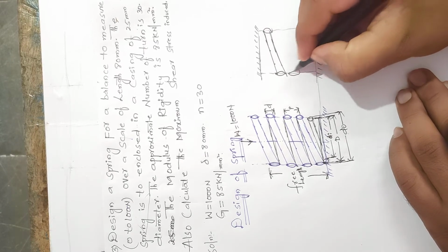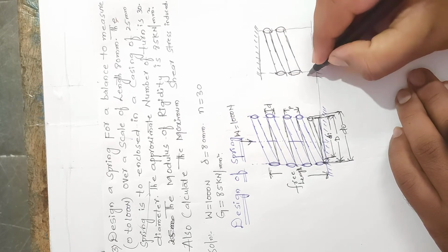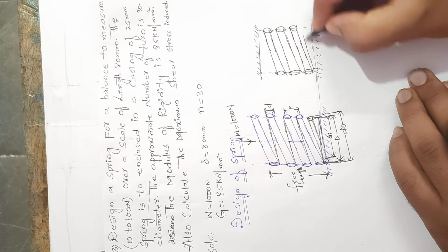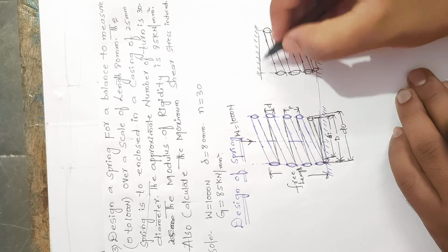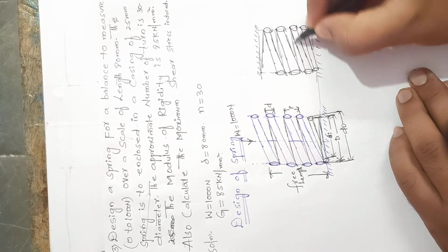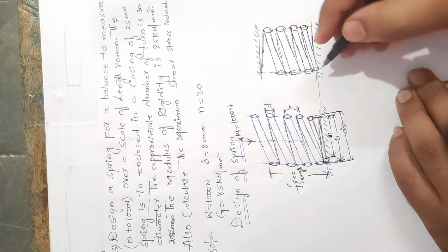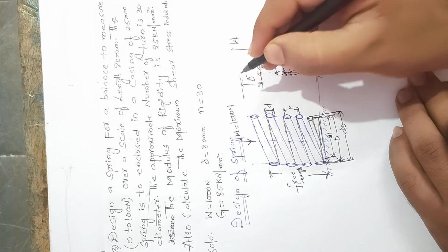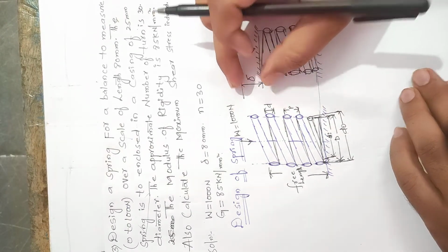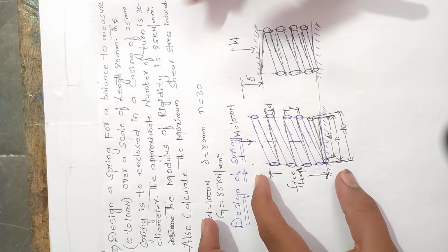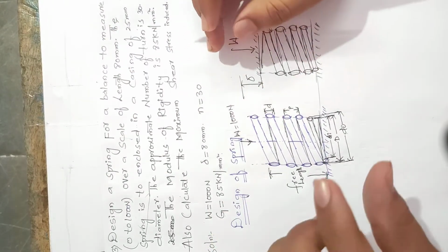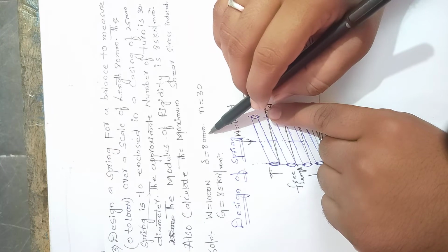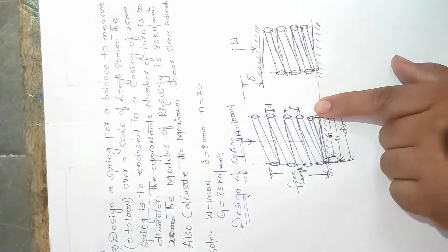This is the spring. If you apply the compressive force on it, it causes deflection in the spring, which is represented by delta. Before loading, the figure should look like this. If you apply the compressive force on it, the spring becomes compact in shape. It should decrease by 80 mm due to the applied 1000 Newton on the free length of the spring. Is it right?